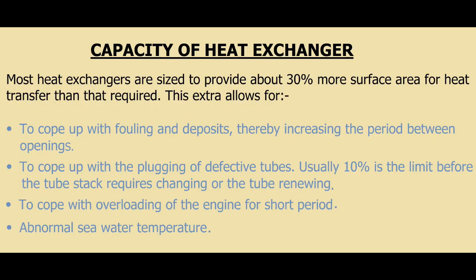Deciding the capacity of heat exchangers. Most heat exchangers are sized to provide about 30% more surface area for heat transfer than that required. This extra allows it to cope with fouling and deposits, thereby increasing the period between openings.